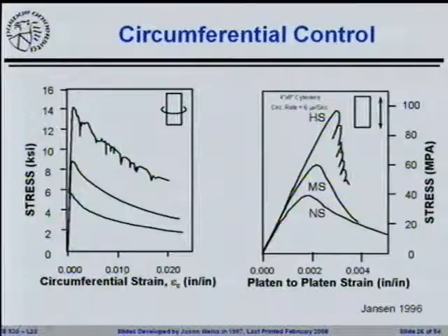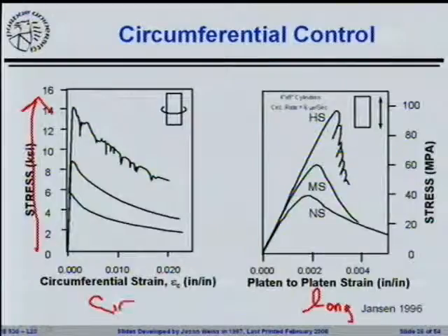Here you can see the stress. These are stress-strain diagrams. On our y-axis, we've got the stress for both the cylinders. On our x-axis, you've got the longitudinal strain. On the right-hand side, you've got the circumferential strain on the left-hand side of the diagram. And this is a case of what we were just talking about, where you might want to jump ahead very quickly because there's not a whole lot of expansion happening in the circumferential direction before you get to peak, because cracking is relatively small.